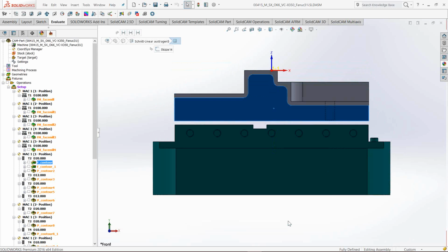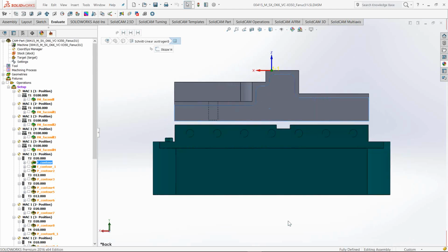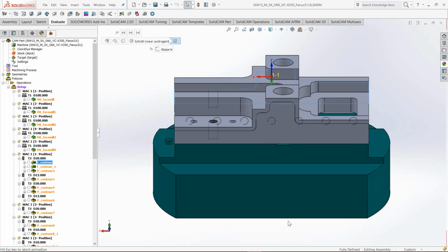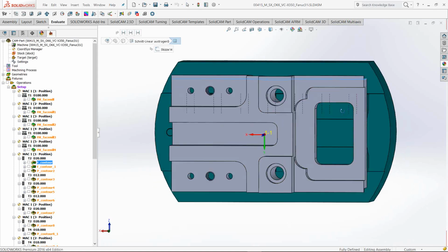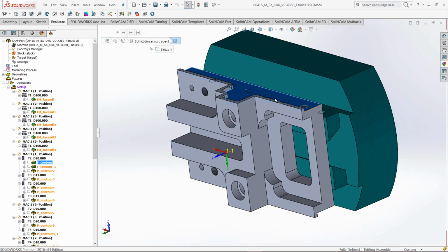And the second angle pair, how you can get it, pay attention. I will rotate around the C axis 180, and then I will rotate minus 90 degrees. Then again we get to the same surface to machine it. So in 5-axis machines, every surface can be reached with two angle pairs.